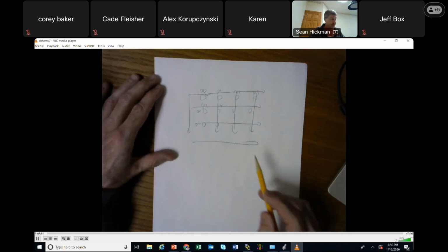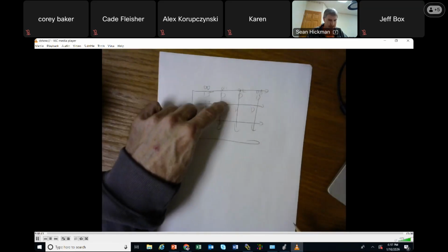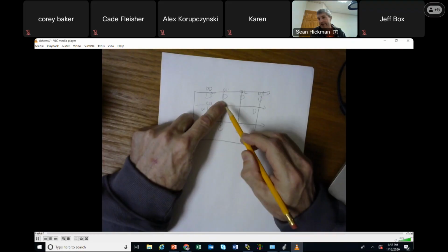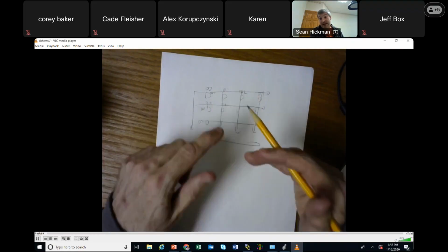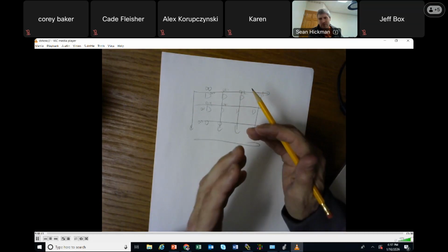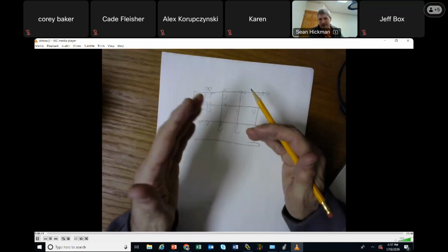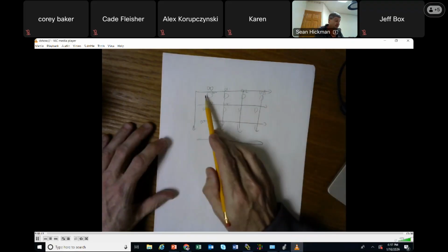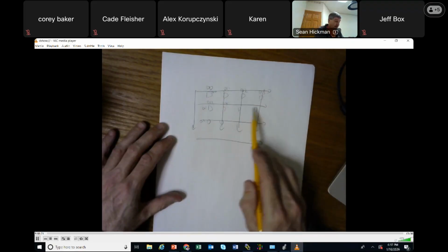And so you're thinking, hey, I'm pushing this button, and this light's coming on. How come this light's coming on? It's a lighted push button, and they've wired it so that they have nothing to do with each other. The input's wired into an input, and the light's wired into an output. And it'll screw you up. Inputs run this way and outputs run this way.